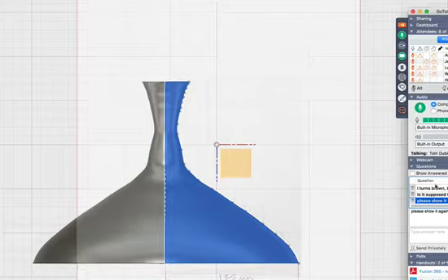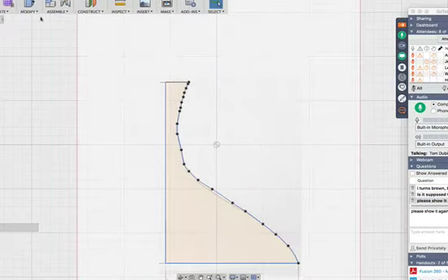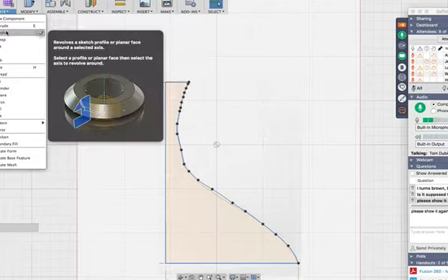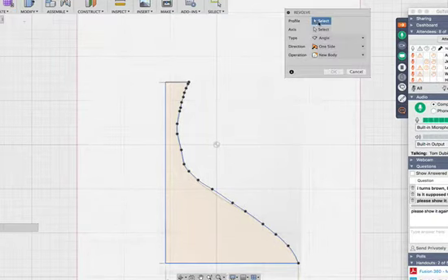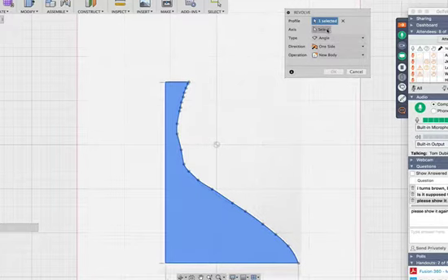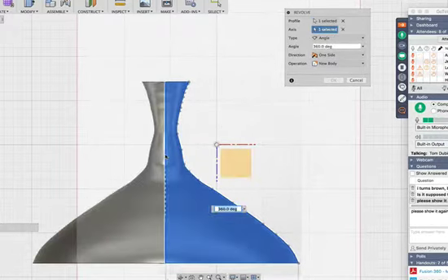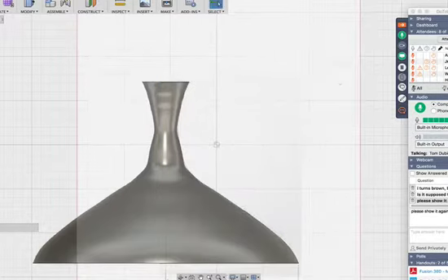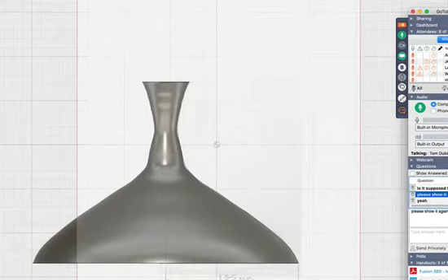Did that make sense then? Did it work for you, man? Let me show everybody what I just did. I go to create, I go to revolve. First one is the profile. It's already blue, so you can select it here. But for the axis, hit select first there, because you're telling it, hey, I'm going to the axis now. Click there. Okay, and then you have it. That's it. Good. Love it when a plan comes together.